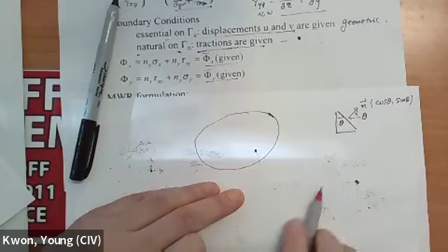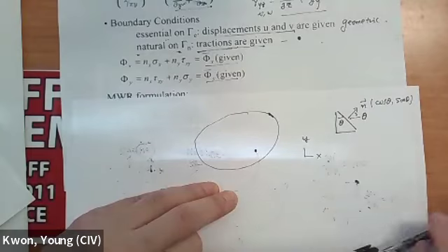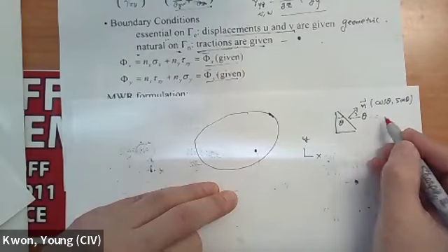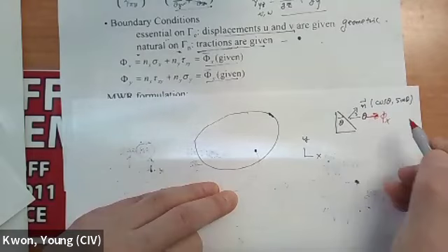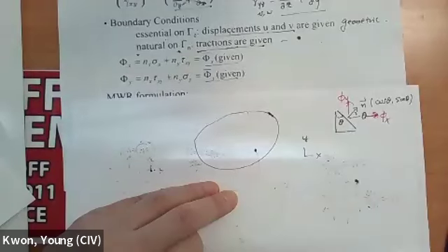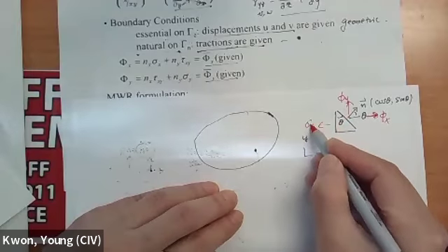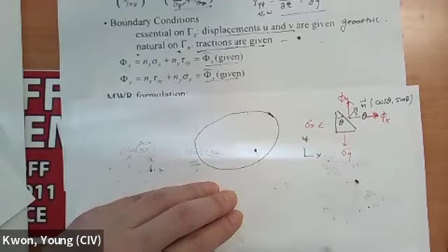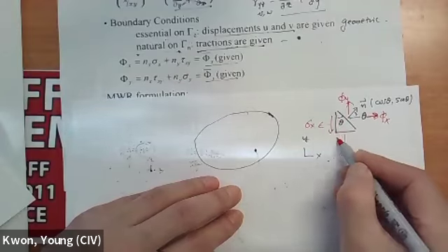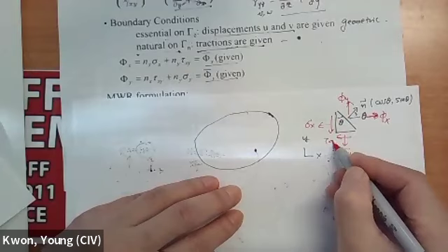Okay, and the traction, since we use the XY coordinate system again as usual, horizontal X, vertical Y. So let's say this is traction Px, and that's the traction Py, on the surface. And here, normal stress is sigma X, normal stress sigma Y. We assume positive based on our sign convention, tension. And then shear stress, again assuming positive direction, that's going to be tau sub xy, okay?